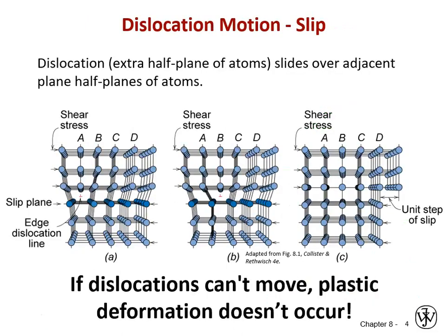Okay. Looking back at our friend the edge dislocation. So we're back to looking end-on at a metal crystal lattice here, and you can see that over on our left-hand diagram we have an edge dislocation, and that's the plane of atoms labeled A, second from the left within our crystal, and it ends 3 atomic rows down from the top of that schematic.